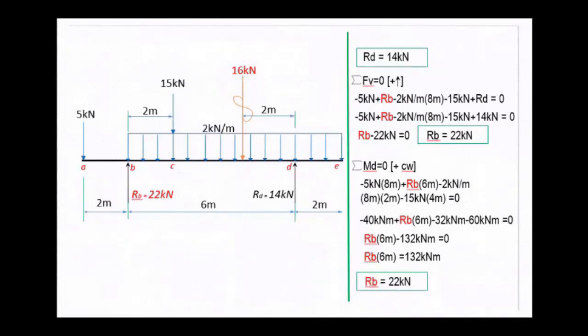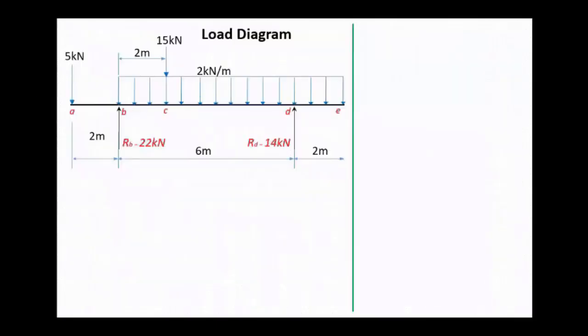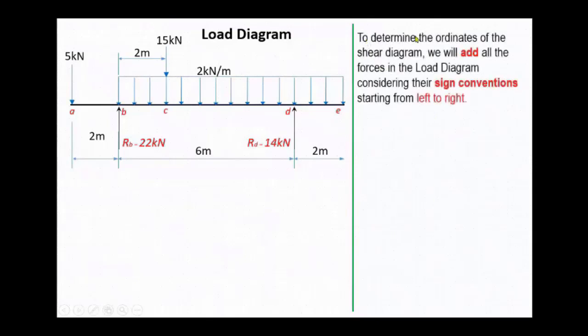So we are halfway in drawing the shear and moment diagram. To recap, first, we assign variables in the location of loads and location of the supports. Then we remove the supports and replace them with their corresponding forces. Then we resolve those forces using the three static equations, the summation of moment, then summation of forces. Now we will draw the shear diagram.